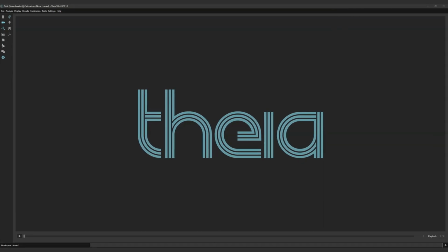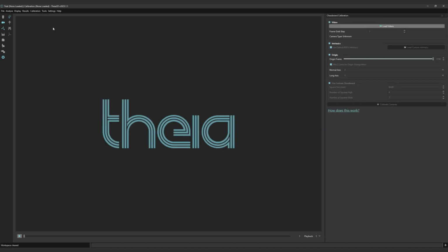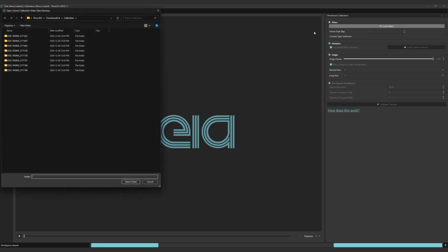If your video data is not yet organized, you should watch the Organize Videos tutorial and complete that step before proceeding. If you are using OptiTrack Prime Color cameras, you should have a lens calibration.txt file. If you do not have a lens calibration file, you should watch the Processing Lens Calibrations video and complete that step before proceeding. First, navigate to Calibrate Chessboard under the Calibration drop-down menu.